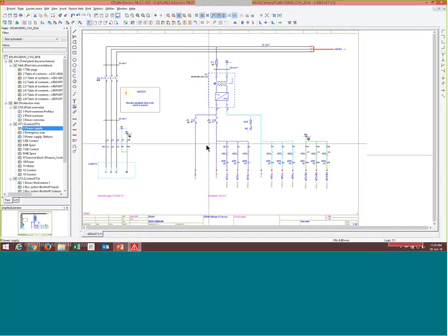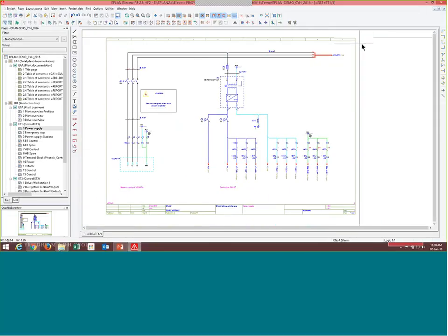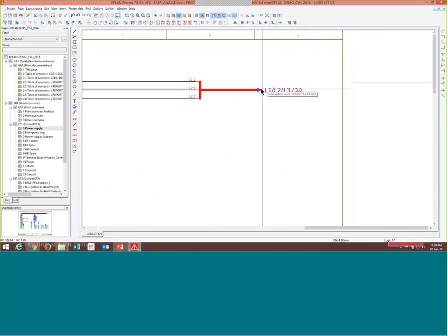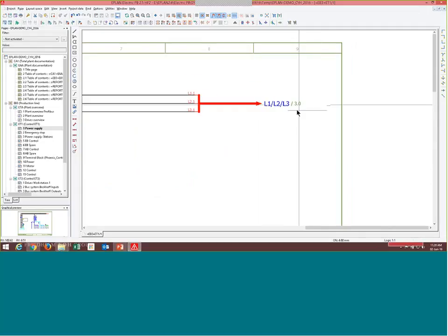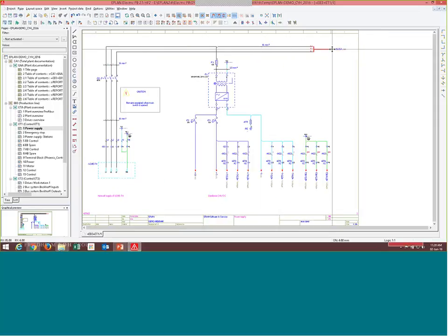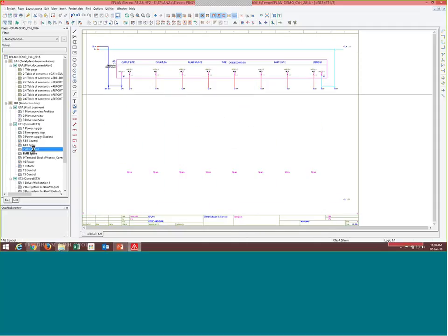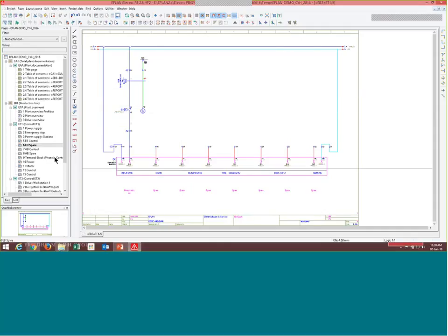The next one will be the cross-reference. This is a multi-line drawing. Of course you have an arrow to show you the next incoming is going to which page. So this is going to page number 3, title block column 0. You can just press jump. So basically they will jump from the source to the target. It's very easy for you to track the source and the target. So this is the example drawing.